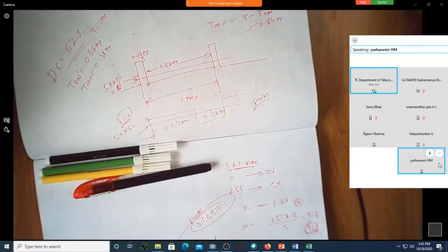Sir, in the program we use delay(1000). Why do we have to use that, sir? You want to blink the LED, so it should be on for some time and off for some time. What does delay 1000 mean? Whenever a program is executed, before you go to the next statement there is a delay of whatever number we specify, in milliseconds. Yes, sir, 1000 milliseconds it will halt. The program will not proceed.